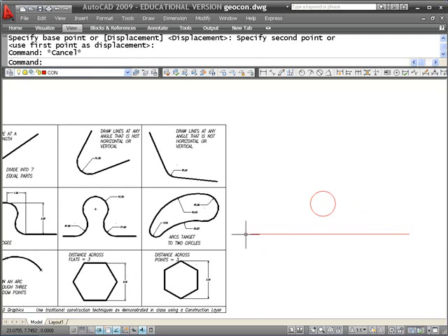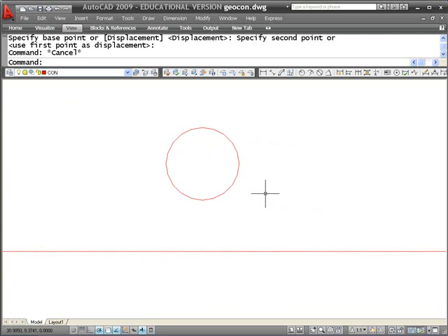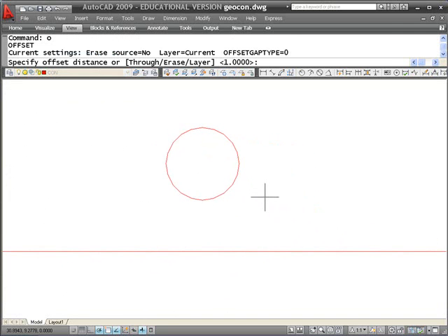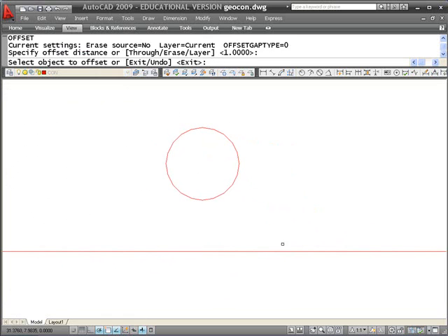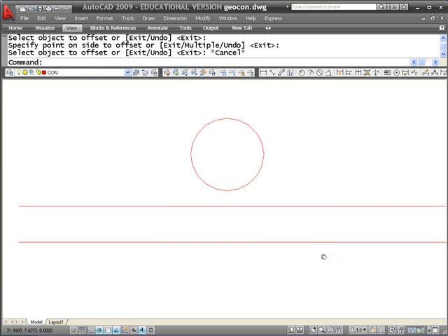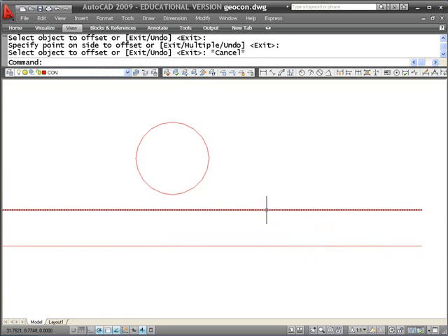So these are random. That line was randomly drawn. The circle was drawn at a specific radius of 1, but its location is random. I'm going to connect it to the straight line using two arcs that are also given a radius of 1. So zoom in here. First thing I'm going to do is to offset 1 unit and bring that line up here. That means that parallel line indicates the center of an arc that is 1 unit away from there.